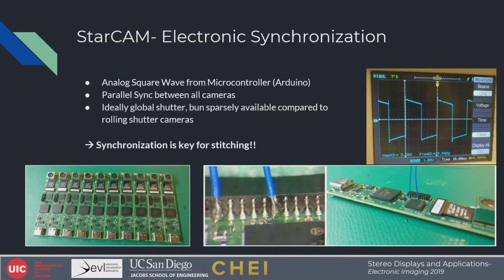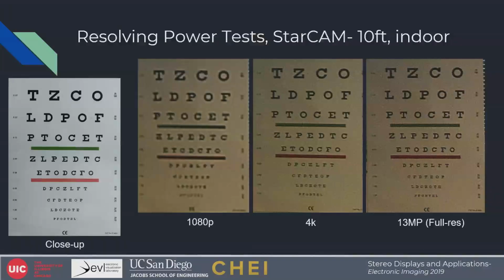As I mentioned, having correct synchronization to the rolling shutter was crucial. These cameras were a little unique in that, with some experimentation, we're able to electronically trigger the cameras so that every readout of pixel row along all 16 cameras was perfectly synchronized.